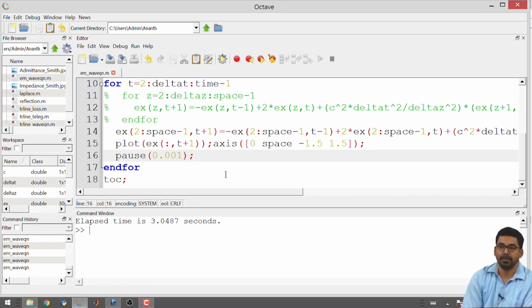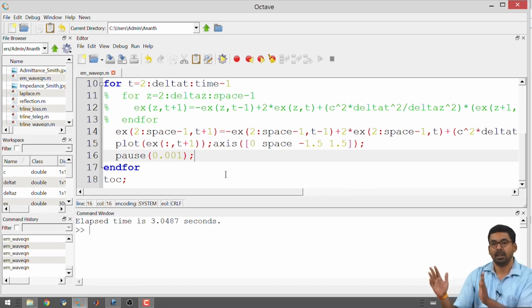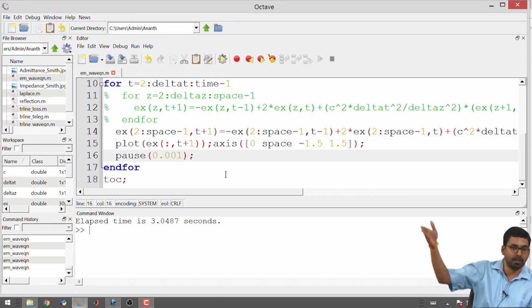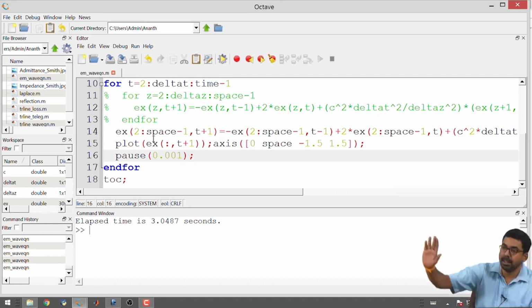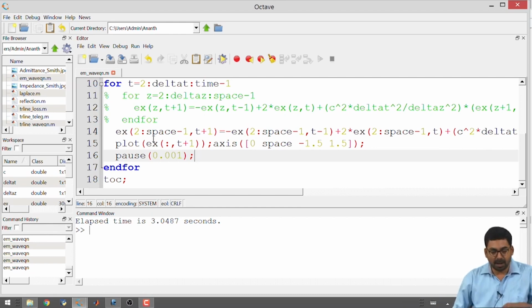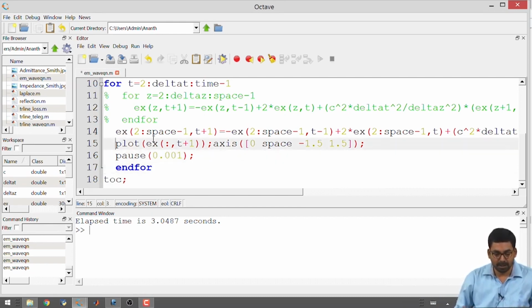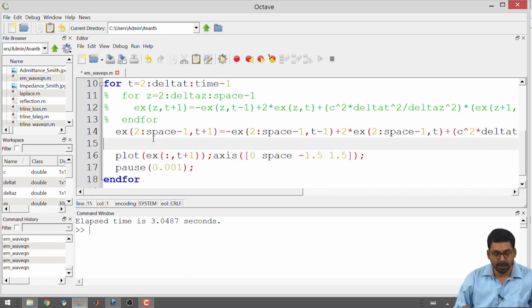In the case of transmission line, you used a region to absorb the wave. So, that can be some kind of an absorbing condition, but it is not really a boundary condition. It did not happen at the boundary, it happened over a region. Can we make a wave disappear from the simulation region from one side to another side without it coming back? This needs a little bit of imagination. So, since we are concerned only about the point at the right extreme, we can write down a piece of code that looks like this, and then try to analyze what it is actually doing.